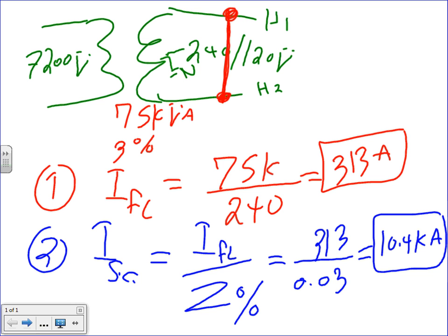What does that mean to you? Now, Spencer, I need you to size me a circuit breaker here. In the book it says kVA times 1,000. Because we multiply by 1,000 here; you're just converting from kVA to VA.